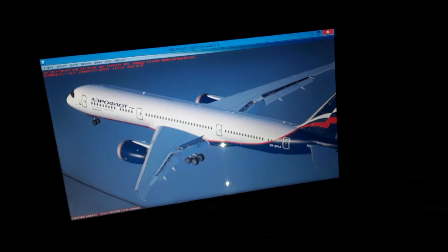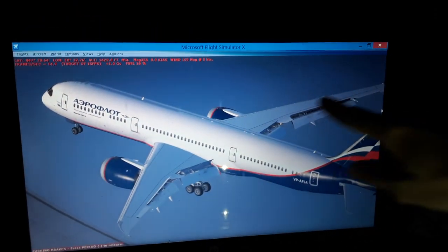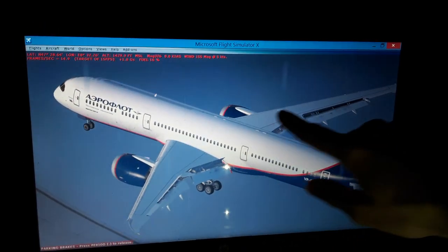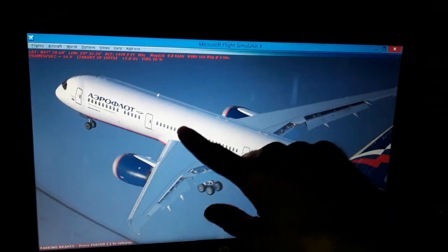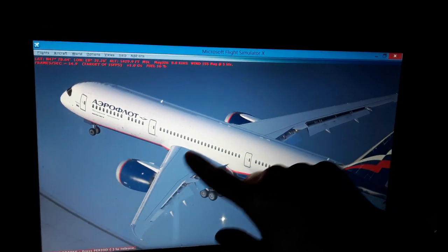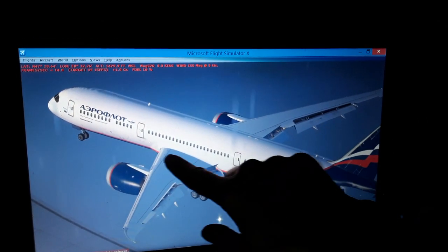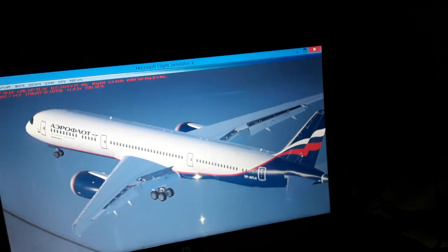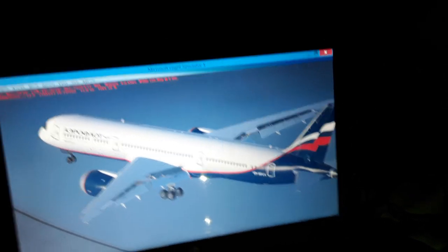So as it tells you, thrust from the engine. You can see here we have the mean aerodynamic chord position. In the forward wings is where the maximum aerodynamic lift occurs. It's 23% of the chord of this aircraft. It is where the maximum aerodynamic lift occurs in the wings, and you need to know that if you're flying aircraft, it's also where the stall will begin in flight, for an angle of attack that is different for each aircraft. Maybe weight and airspeed is different also as you're flying faster and slower.